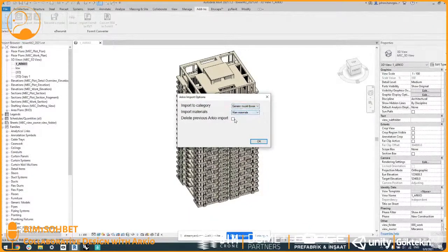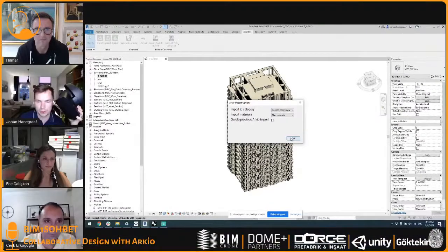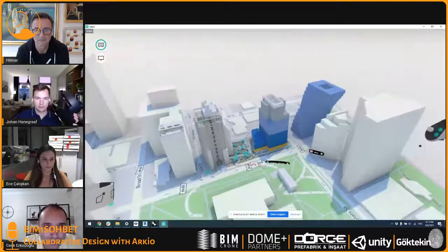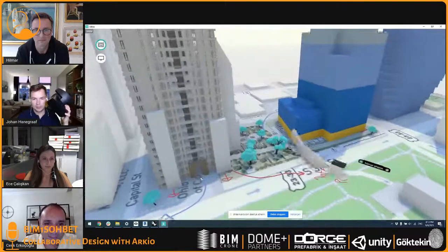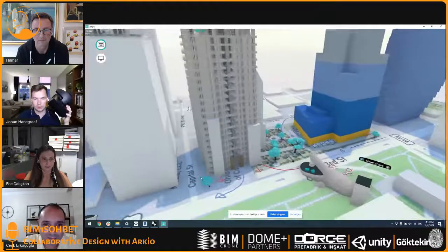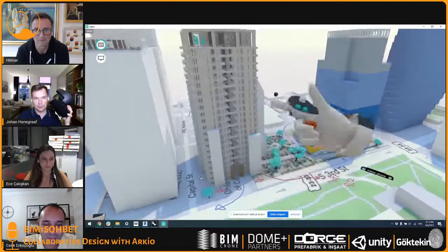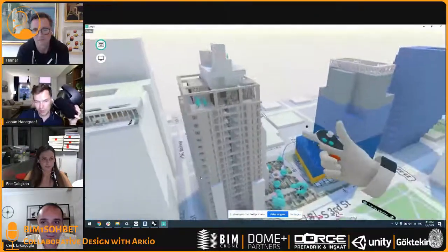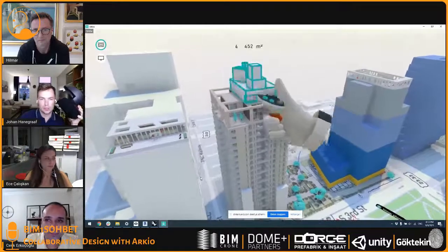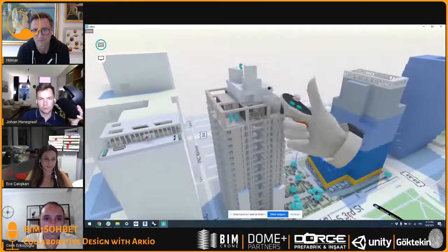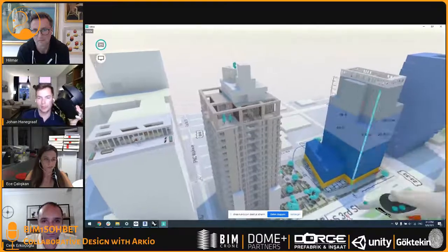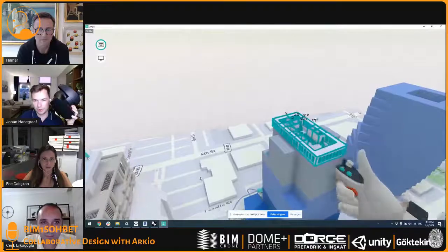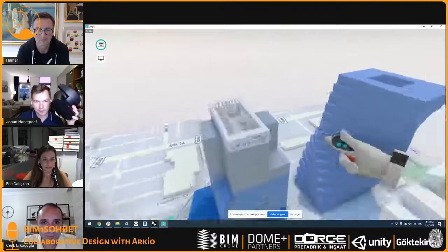Generic models gives you the individual objects that you work with. And what it does is everything that we see here in Arkio, every object that got placed, so for example that tree or some of this geometry that got made, gets converted to native Revit components or Revit families. And this solid geometry over here will be converted to direct shapes in Revit. So you can directly keep working with that geometry, and this apartment that we have in here will all be included in there as well.